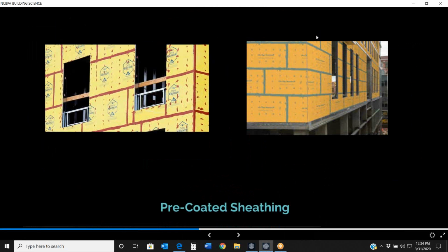However, integrating a weather-resistant barrier and then being able to seal those joints with either fluid or tapes, sealing our penetrations if necessary, and our fastener locations if necessary, this can really be a time saver. When the sheathing goes up and the joints are sealed, the building's done.